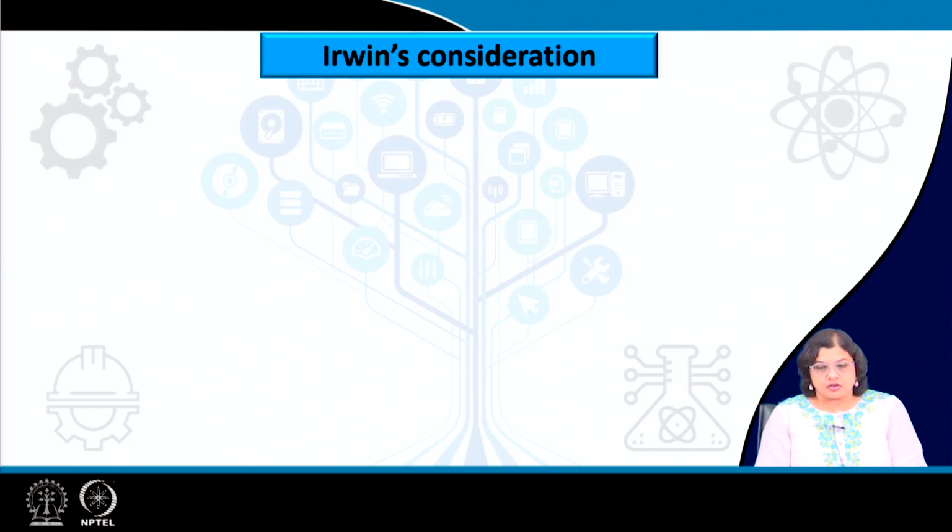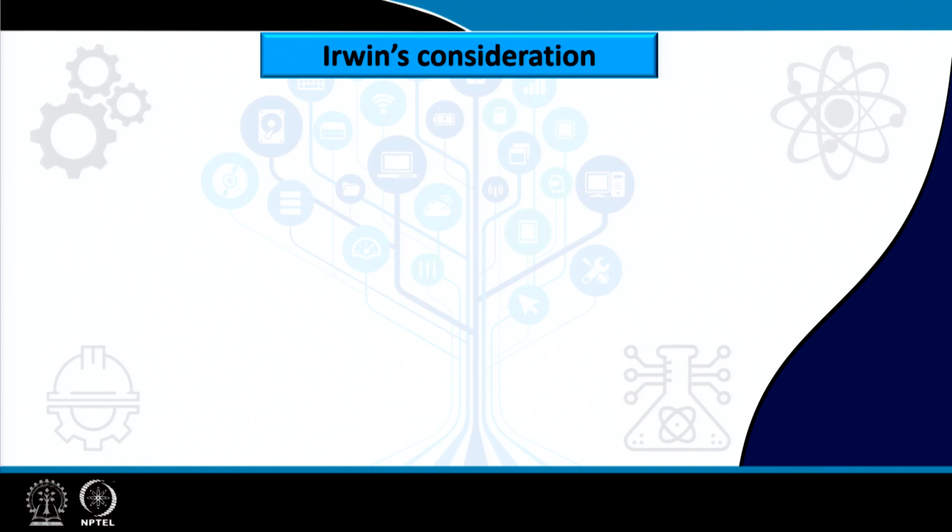Okay. So, now that we have seen how Orowan has tried to modify the Griffith criterion to include the plastic deformation energy, we have also seen that there are some drawbacks. The plastic deformation energy is very difficult to determine experimentally, which calls for some other kind of modification, so that we do not need to determine the plastic work energy, but still can quantify the amount of stress that is required for fracture to initiate.